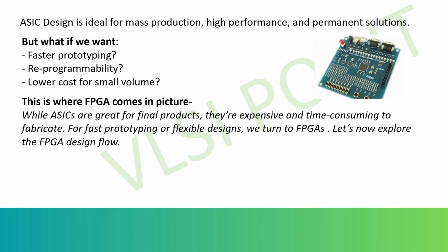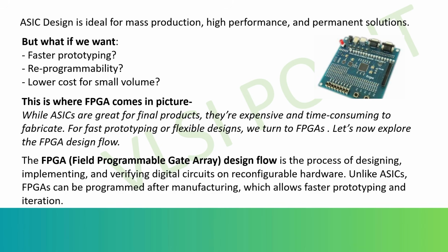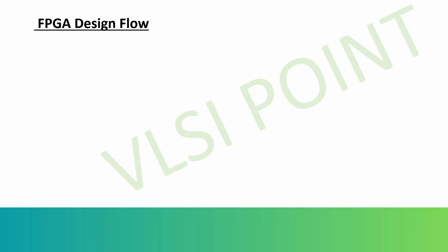Then you must have design tools like Vivado or ModelSim to test your code on the FPGA board. So basically, you can write the code for any of your circuits and test the working of that code on the FPGA board. That is very affordable. Most of you have already seen that FPGA board in your college lab. You can connect that FPGA board, dump your program and test the functionality.